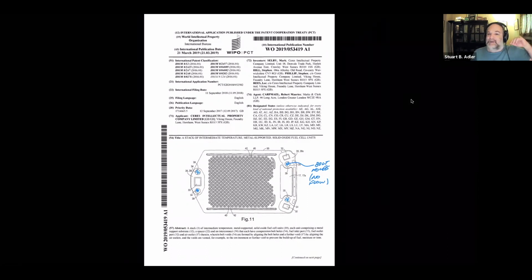And that could be bad if you think about the utilization, because the current is the same. Current is going through every cell. So I'm using up the same amount of fuel on every single cell. But if I use up the same fuel on every cell, but I'm feeding less fuel to some cells than others, it means the utilization is higher on some cells than others. So some cells might be going to 90% utilization, while other ones are down at 75 or 80% utilization.